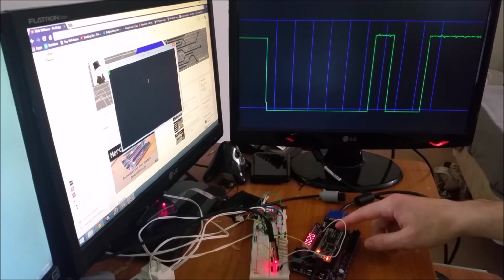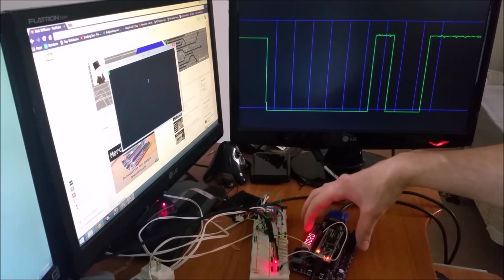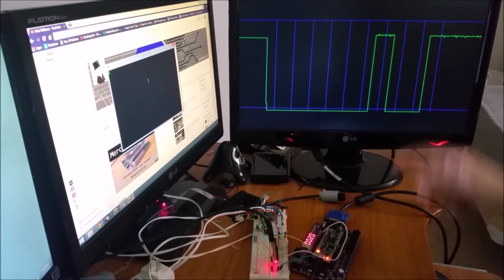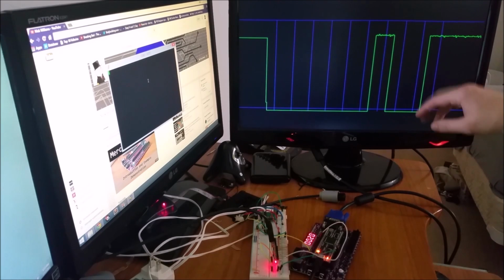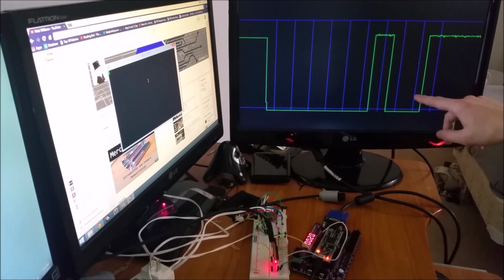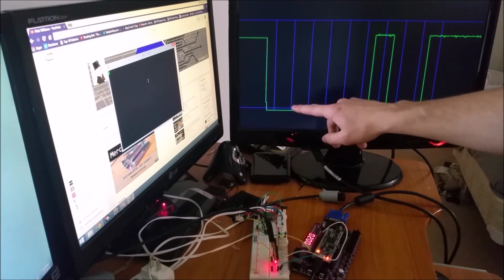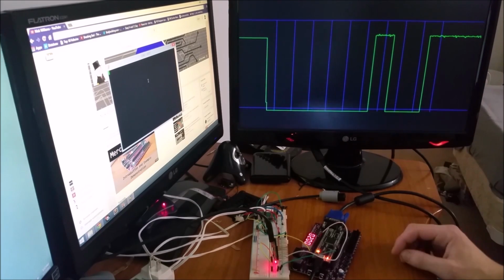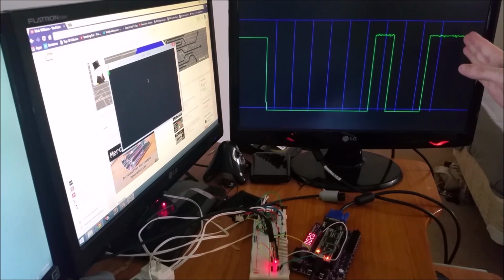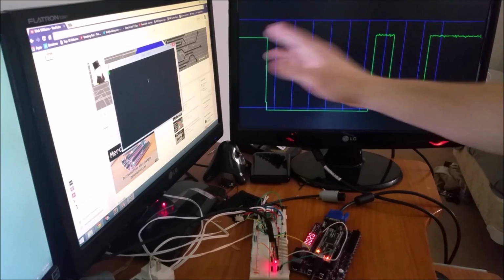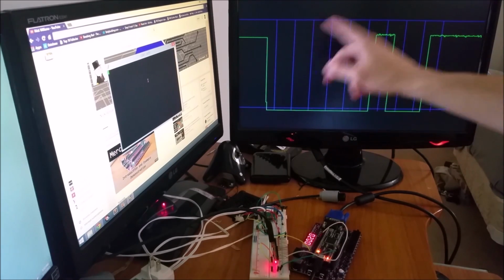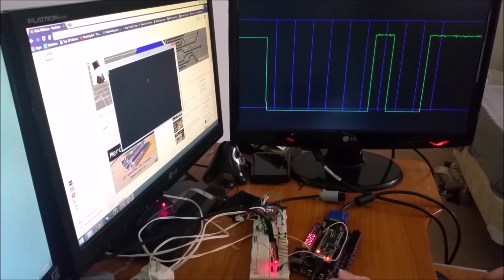and you can see, it might be a little difficult to see, but 20 appeared on the 7-segment display, which is the ASCII character code for the spacebar. And you can see 20 appears here, the most significant bit starts here, and then it goes to the least significant bit here. As I said before, this is the start bit and stop bit. And you can see I have about a 100 pixel cushion on either side, and so the waveform fits really nicely and perfectly within the VGA monitor, at least horizontally.